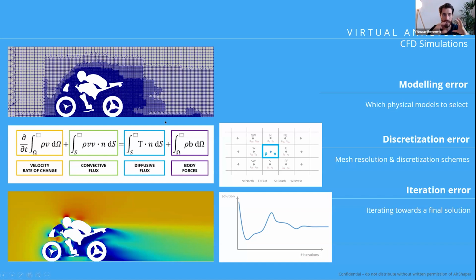So for CFD, once we have our grid, our cells, our mesh, basically, we will solve that set of equations. So every cell will have a number of equations that need to be solved. So for 1,000,000 cells, you have maybe 5 million equations that you need to solve, because every equation will link what is happening in one cell to the neighboring cells by linking the pressure, by linking the velocity, by exchanging data about flow rates, and so on. So there's a whole lot that you can actually do to still influence the accuracy, even once you have the mesh. It still needs to be solved.